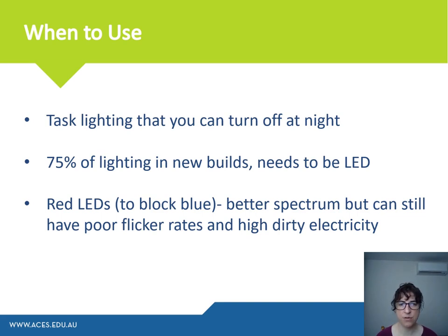75% of lighting in new builds in Victoria anyway needs to be LED lighting. So that's the consideration I mentioned before, when you're talking in building design to the electricians and the people working on the project, they're going to say, well, you actually have to have the 75% LED lighting. So then you need to look at whether they can put it in and retrofit later, or what you can do with that lighting so it's not used in places where it'll be turned on at night, so that you can actually turn it off and use lamps.